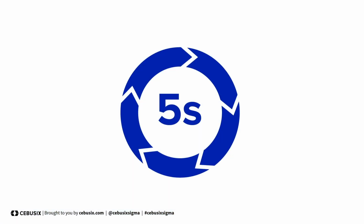The 5S tool plays an important part in the Lean methodology, and its implementation is a prerequisite to just-in-time manufacturing. Originally, 5S included sort, set in order, shine, standardize, and sustain. But today we have added a 6th S, which is safety. When sorting, we are removing any unnecessary items from a location. Setting in order requires finding the optimal place for an item or process. Shine means always keeping the workplace clean and orderly.